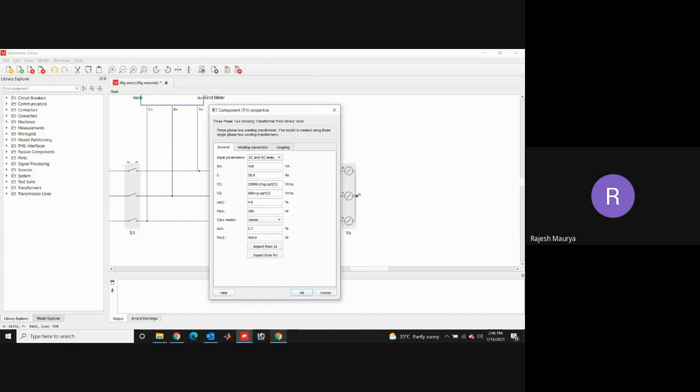One thing I'd like to add over here: in this constant block or gain block, whenever you need to write any pi or square root, then you need to write np dot square root. But if you declare pi in the C function block, then you do not need to write np dot pi over there, because it is not based on Python. Its syntax is similar to C. So that's why you do not need to write np over there. That's the difference.